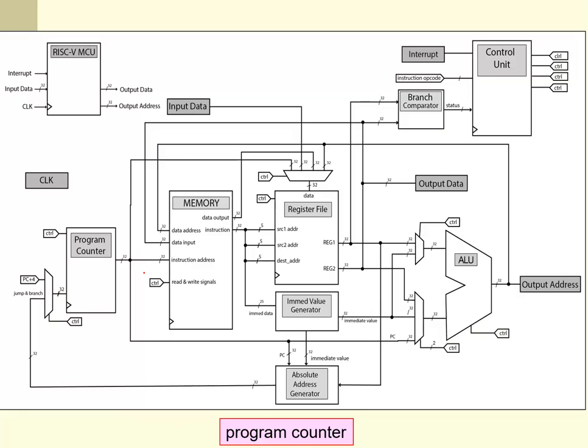And there's a control unit. Next thing we have is a program counter. So we've talked about this before. The output of the program counter is this thing, and it forms the address of the instruction that is being implemented. That's the general definition, but quite frankly, depending on when you look at it, it's the address of the instruction being implemented. Sometimes it's the address of the next instruction. Like I said, it's kind of hardware dependent, depending how the hardware is implemented.